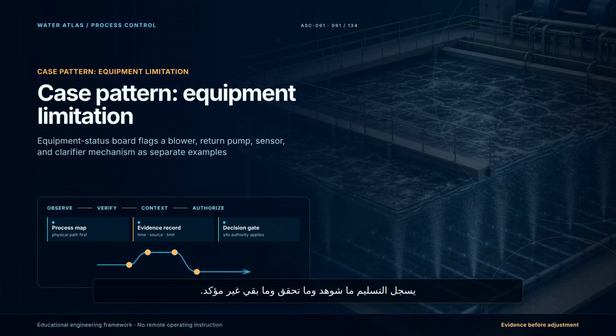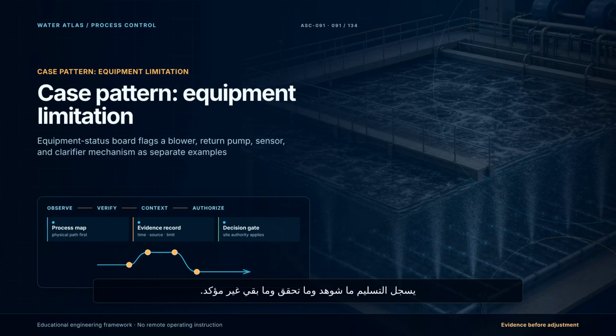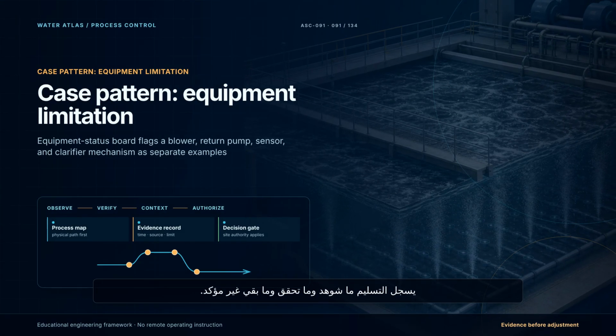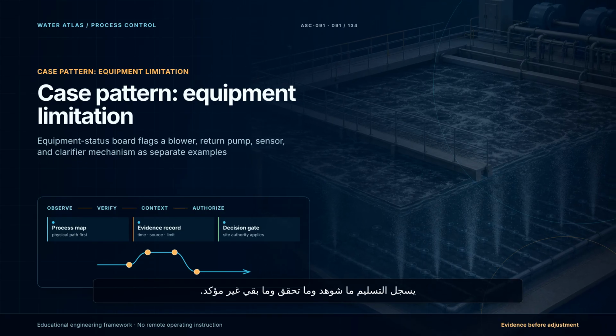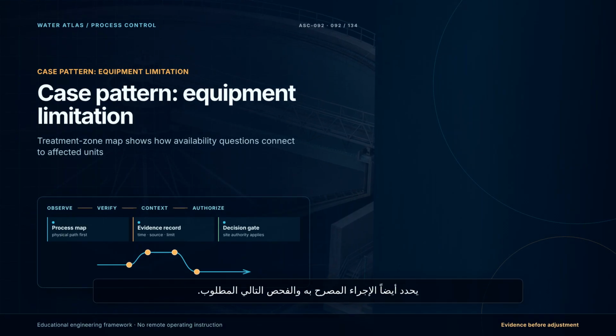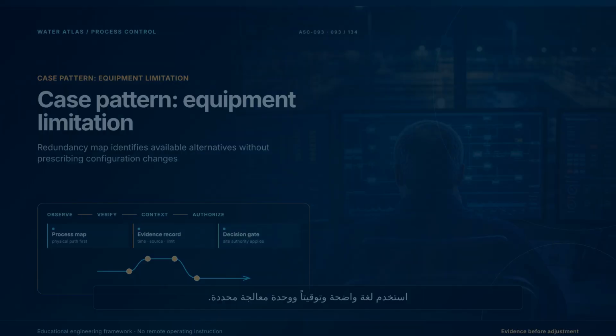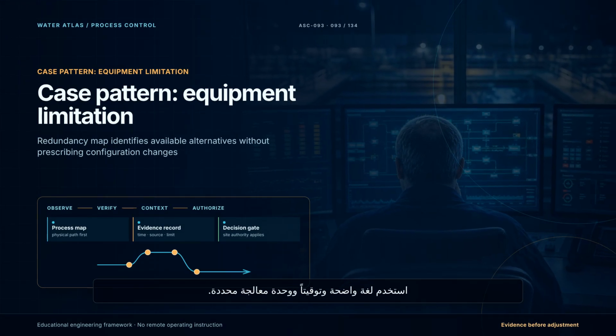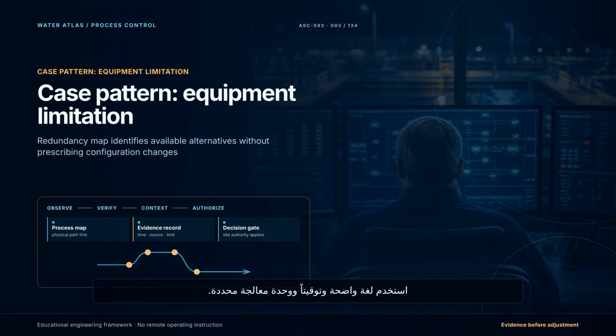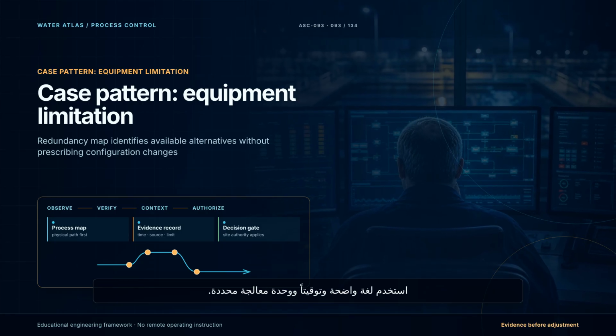Make the disagreement visible. Check instrument calibration and maintenance records. Repeat or confirm sampling through approved methods. Review time alignment. Were all data points collected from the same operating period? Check units, transcription, and calculation inputs. The disagreement may reveal a real process transition. It may also reveal a measurement problem. Either finding improves control. What creates risk is hiding uncertainty behind a single tidy narrative.